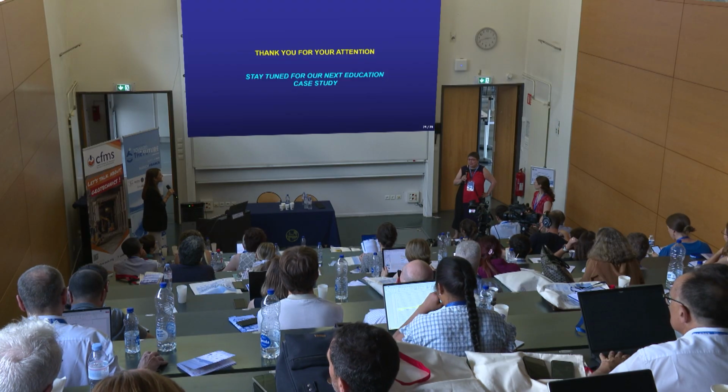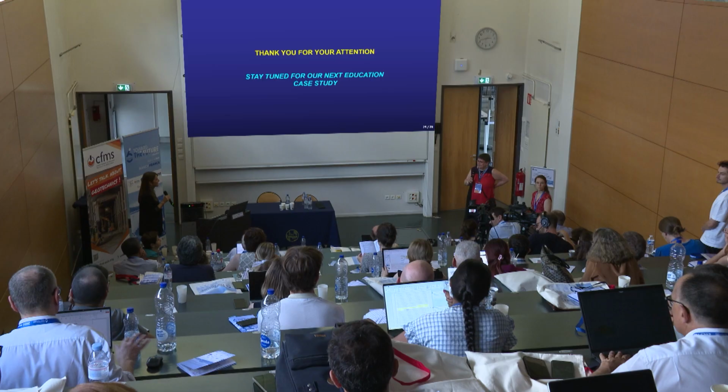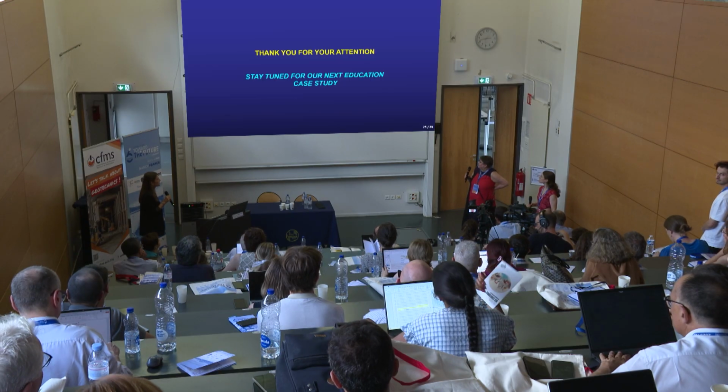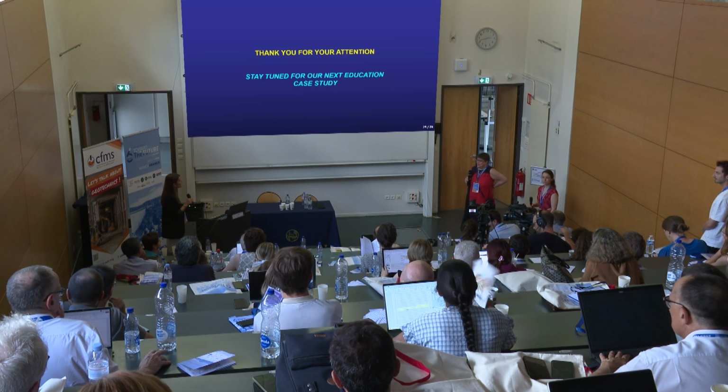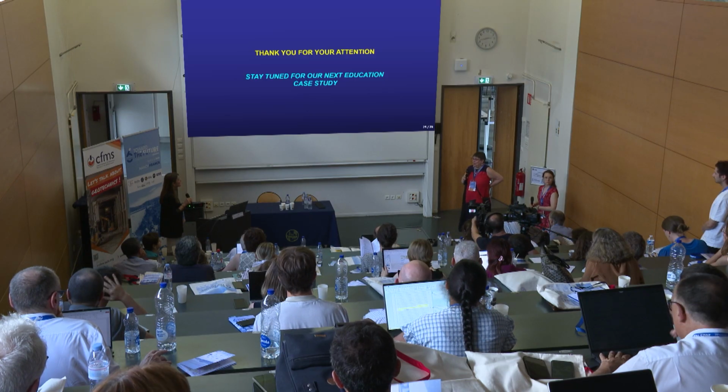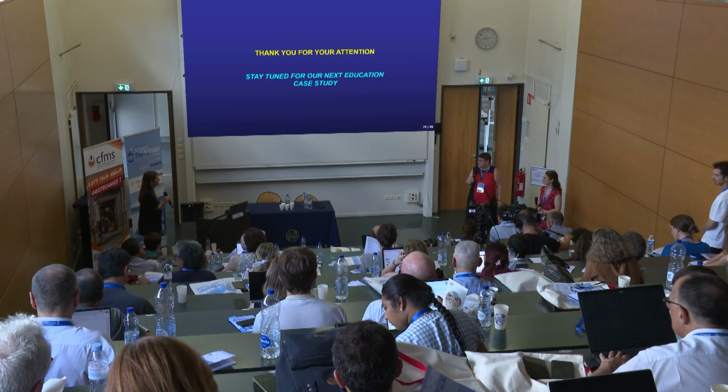I can appreciate that, but where I come from, creep settlements are a big issue, so we don't use stage construction for that reason. It just triggers something which can be as big as a consolidation settlement. So that's one point. And the other thing, in my experience, why we over-predict settlements is sample disturbance, that we are basically always underestimating the pre-consolidation pressure, especially when you have such a layered deposit. Yes, layered deposit, also the pre-consolidation stress, yes.